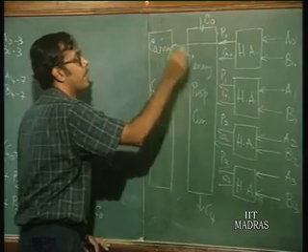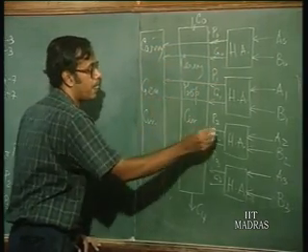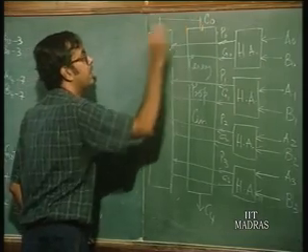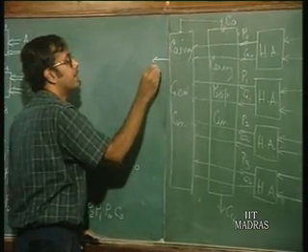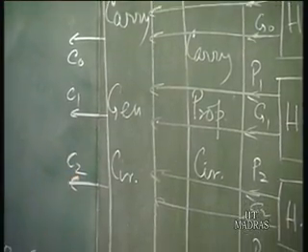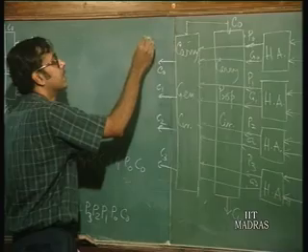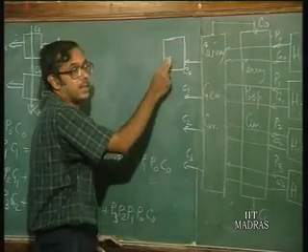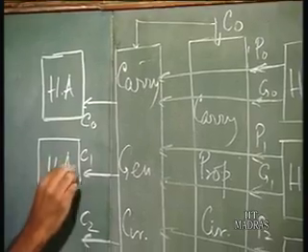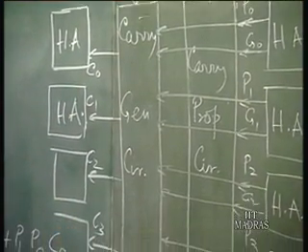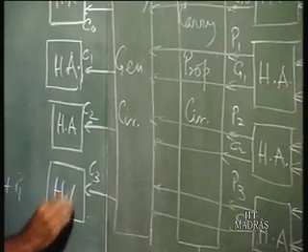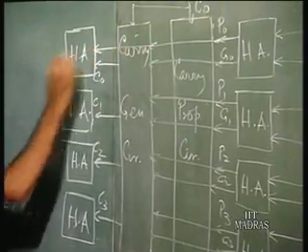So, again you have the different P's and G's coming to this circuit also, and you have C naught also coming here, and what you get out of this circuit is the different carries C naught, C1, C2 and C3. Then you have another bank of 4 half adders, another set of 4 half adders, and these half adders require as input the P's and the C's.